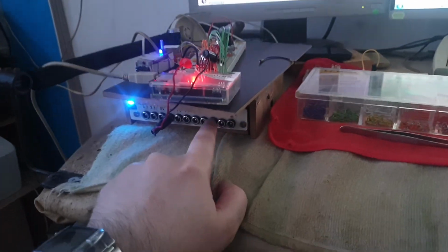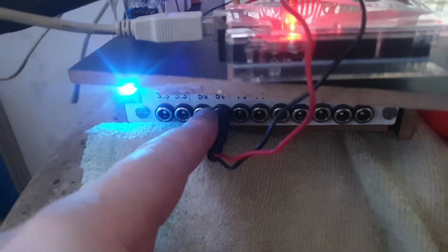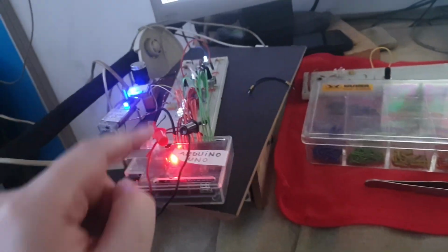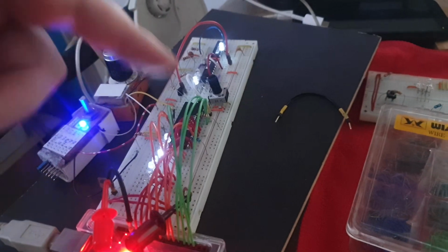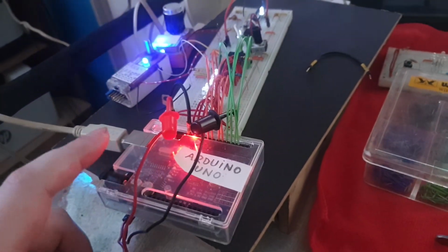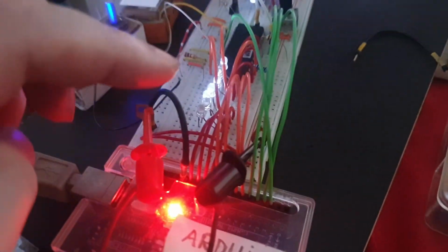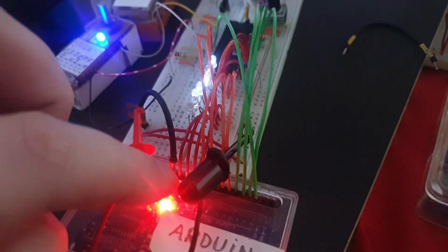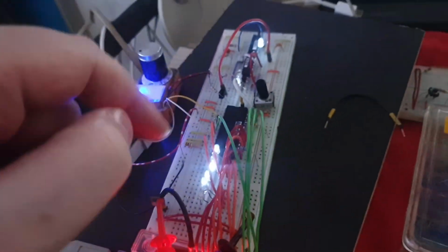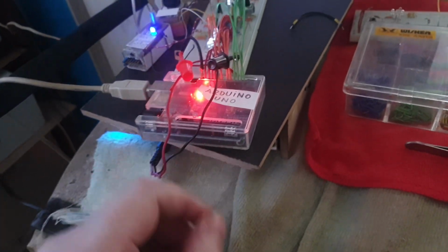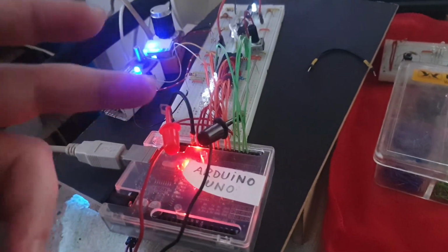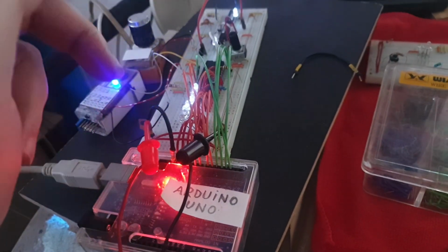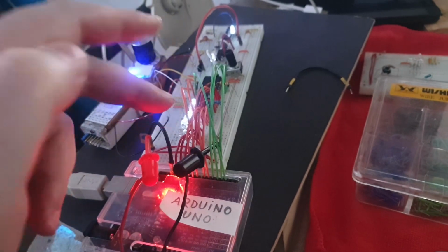This is my power supply that I'm using. I'm getting 5 volts, you see there, from there. These 5 volts are powering this entire board plus these 2 guys. The Arduino is getting the 5 volts from the USB, and I'm only connecting the Arduino negative ground pin to the ground of the power supply. And this is called common ground. The Arduino and that entire board circuit have a common ground.